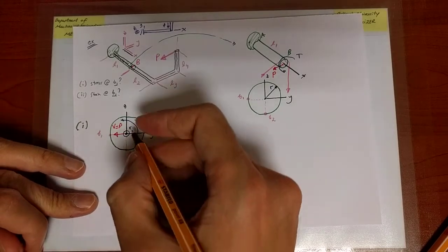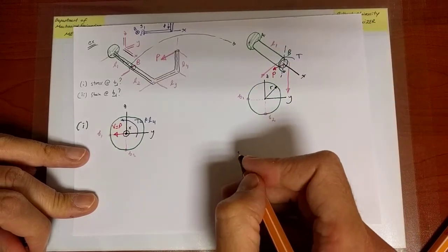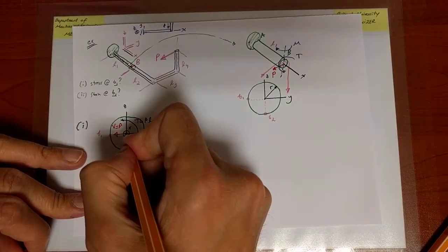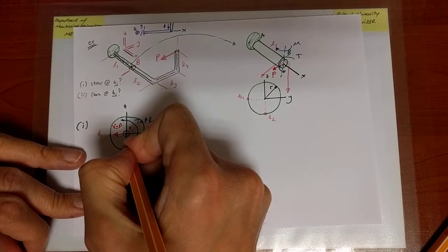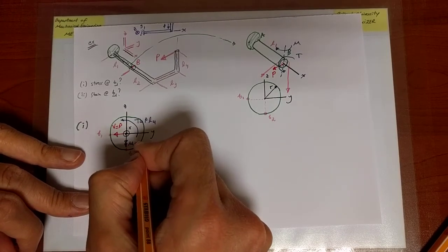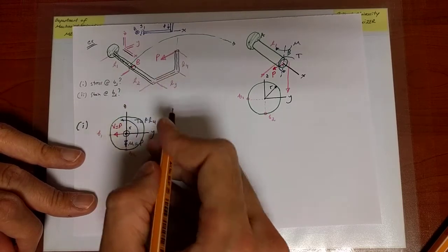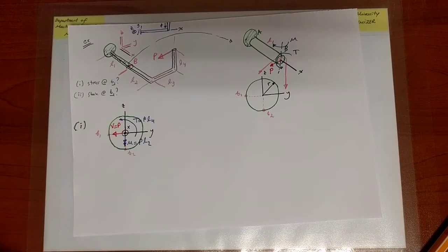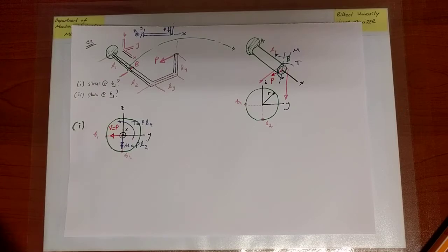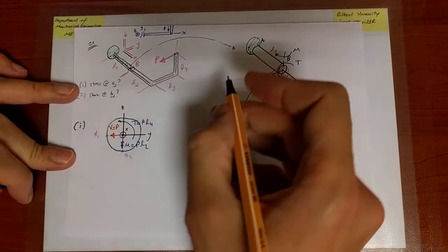So the bending moment in the minus z direction can be conveniently denoted like this. That would be M. Or on that picture, I can draw two arrows to indicate that this is a moment, and M is going to be the force times the relevant distance, in this case L2. All right, good. So that's the statically equivalent counterpart of this loading at cross-section B. And at cross-section B, we are interested in